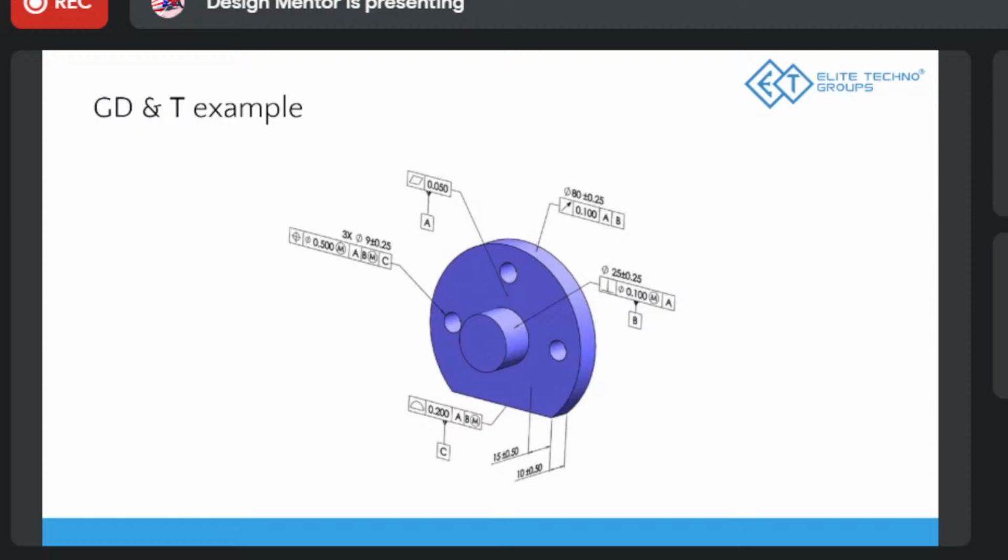Yes, right, correct. I told you, if the maximum material condition is achieved, which for an external part is 25.25, then 0.1 will be maintained. If it starts going away from that, say it is at exactly 25, it is 0.25 away from the maximum material condition. So that 0.25 you add to 0.1, and it becomes 0.35, correct? So that's how you design.